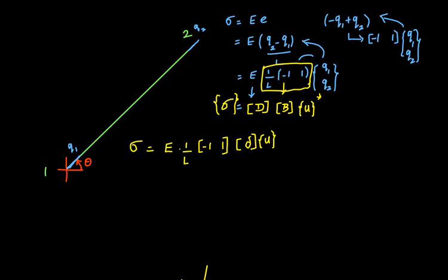This del matrix is the transformational matrix. And what is this U matrix? U matrix is U1, V1, U2, V2, which means the displacement of Q1 along the X component, that is, you resolve it, the displacement along the X direction is U1, and the displacement along the Y direction is V1, and similarly Q2, the displacement of Q2 along the X direction is U2, and the resolved component along the Y direction is V2. So U is U1, V1, U2, V2, and the del is the transformational matrix.